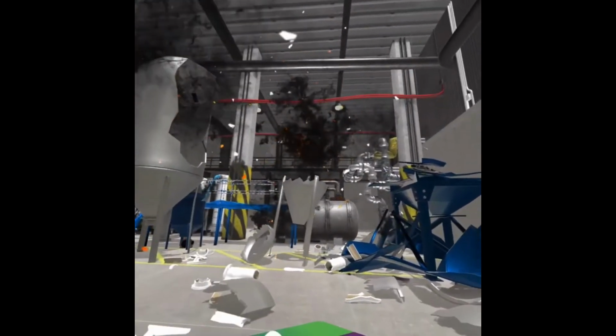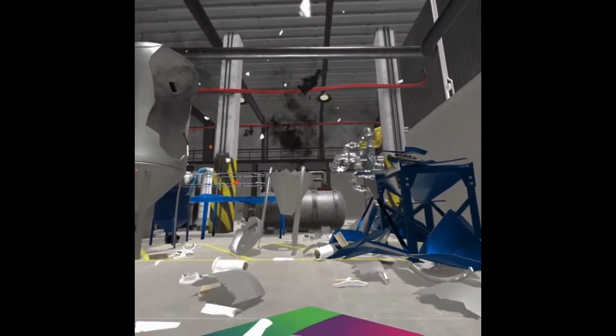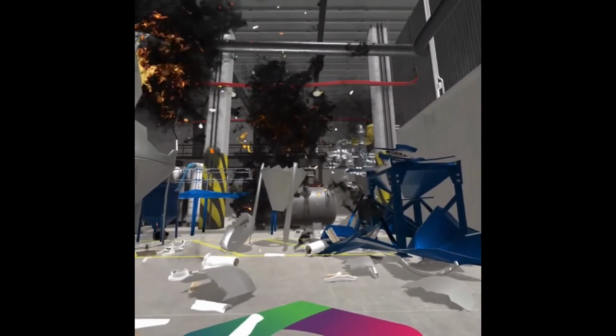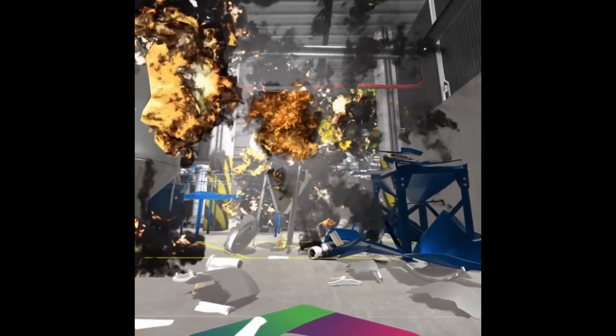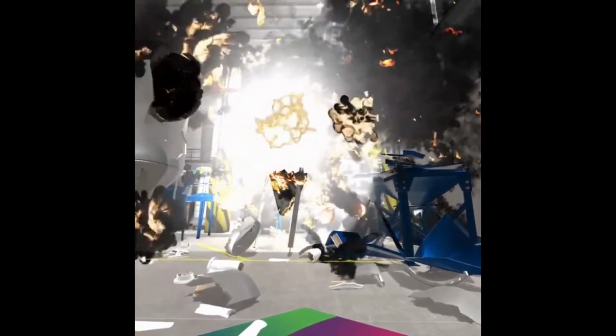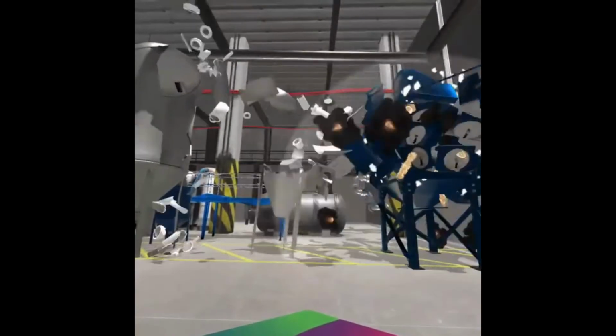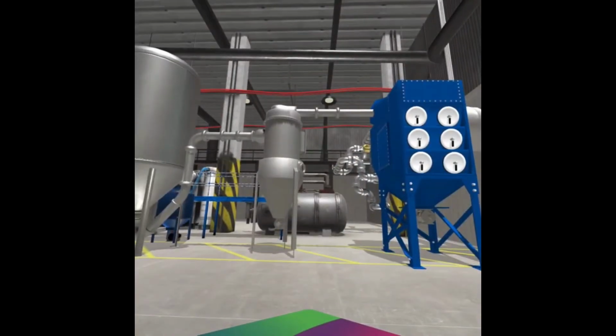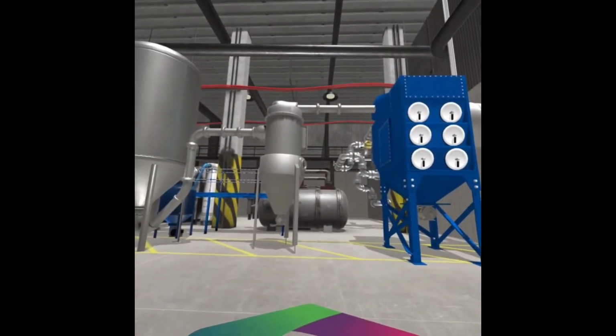The pressure wave and flame front moved rapidly upstream to the interconnected vessels. This propagation from the initial explosion disturbed dust in the plant, which created an even greater hazard. The resulting secondary explosion can be even more devastating than the initial event.